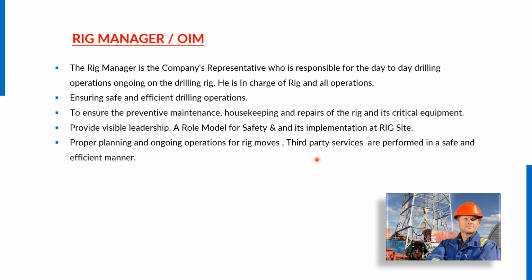And likewise, he has to make all the arrangements for the rig move. For example, if there are third party activities to be done at the rig site, such as well testing, hydraulic fracturing, or multiple other activities, or if there is radiation work, the third party comes and their certifications for equipment, the vehicle daily checklists, and the third party inspection certificates of their equipment have to be checked. So the rig manager or OIM has a lot of responsibilities for the safe and efficient operation at the rig site. And the next is the tool pusher.